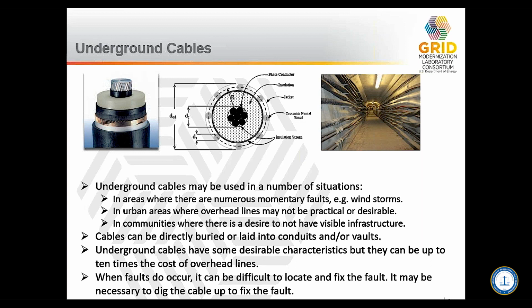Additionally, if you have direct bury lines, faults may not happen as often, but if there is a fault, locating it can be a lot more difficult because you may not see the fault because it's buried underground. And so restoration times can be significantly longer, that's a consideration for customers. Next slide, please.